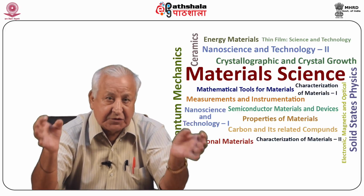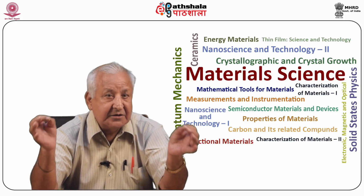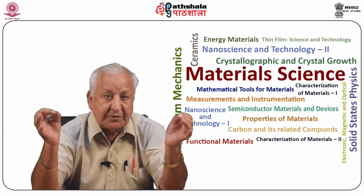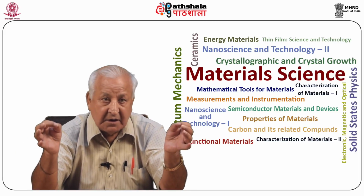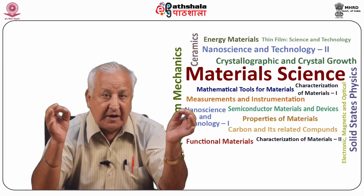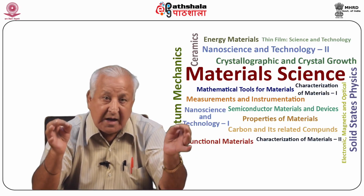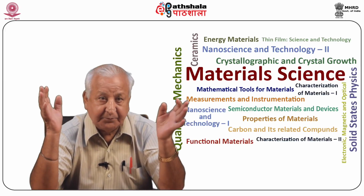The platinum crucible of 6-inch diameter and 10-inch depth is loaded with flux consisting of suitable amount of lead oxide and boron oxide, that is B2O3. To this is added appropriate quantity of aluminum oxide, that is Al2O3, and a small amount of chromium oxide, Cr2O3.